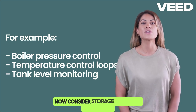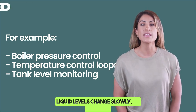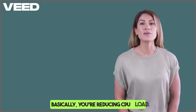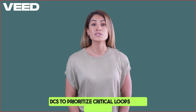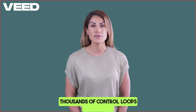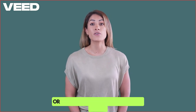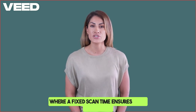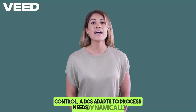Now consider storage tank level monitoring. Liquid levels change slowly, so checking every 2 seconds is sufficient. Basically, you're reducing CPU load. This flexibility in scan time allows a DCS to prioritize critical loops while managing thousands of control loops efficiently. Unlike PLCs, where there are no PID loops or limited numbers of PID loops, where a fixed scan time ensures rapid, consistent control, a DCS adapts to process needs dynamically.